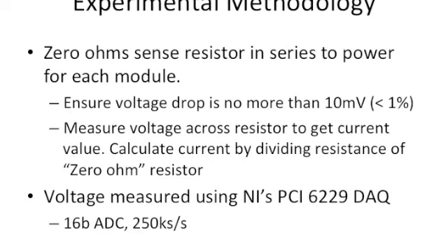If you are just interested in the average current, then you just put an ammeter. An ammeter really gives you the average current. But if you also want to know the time profile of the changes in current, as you turn it on, current goes up, then comes down, etc., then you need a higher sampling rate, and the sampling rate will be determined by the Nyquist criteria, right, for the bandwidths you want to measure.